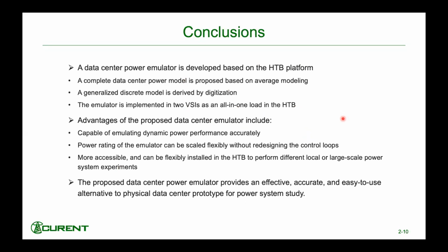You can see the transient waveforms in the terminal voltage or the power. However, the existing work can only predict the static performance, and they do not have detailed modeling of the converter and closed loop controls, so they cannot reflect the transient power or voltage change on the grid terminal.